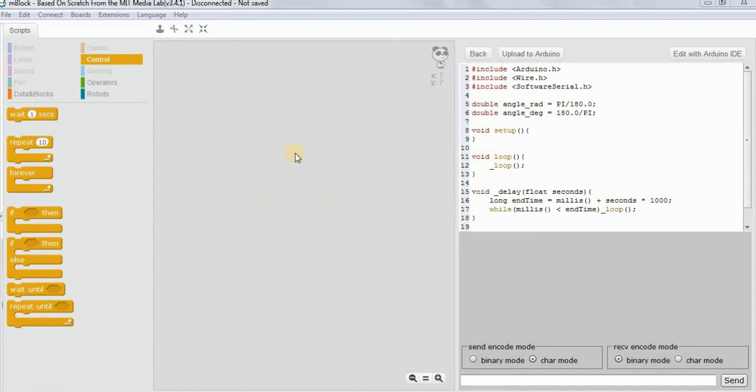So above this is light and below this is darkness. That reference point I can move up or down. And when I'm adjusting that reference point, it is important for me to know the values which I'm getting for certain light conditions. And when we do that calibration, we need the serial monitor to show the values. That is the main usage of the serial monitor.